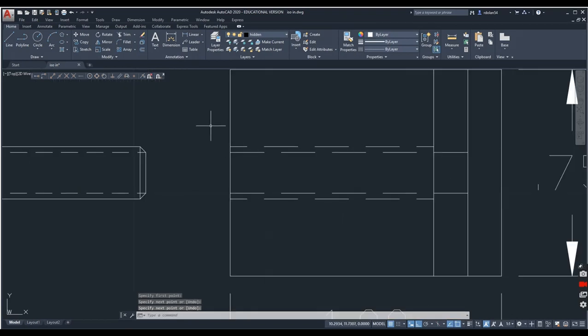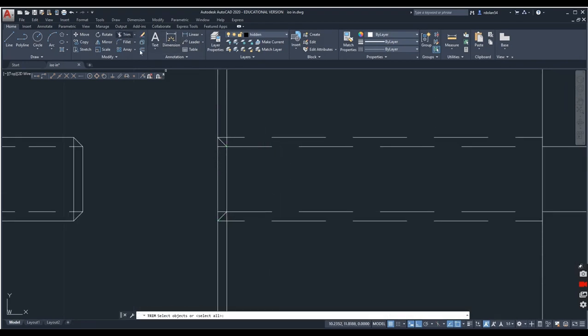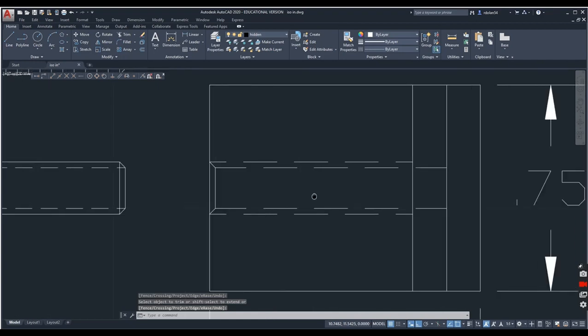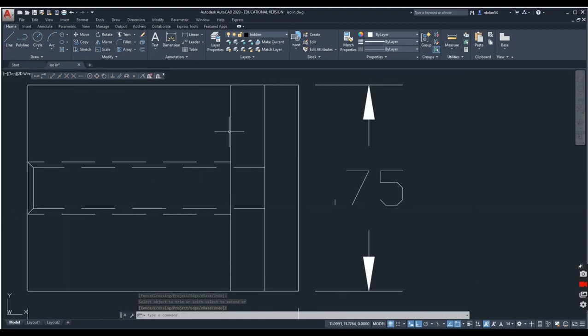Okay, I'm going to offset here because I need to put a chamfer there, so I'm going to offset half the pitch, which is 0.021. And I'll draw a line from here to here. This is my chamfer, and from here to here. Okay, while I'm here, let's trim some of that away. I'll trim this guy here. Whoops. This one, these guys here, and that one there.